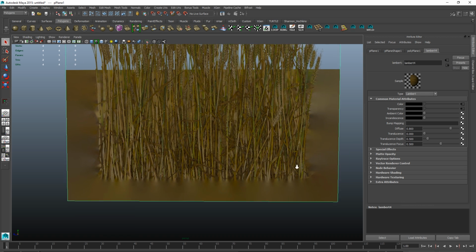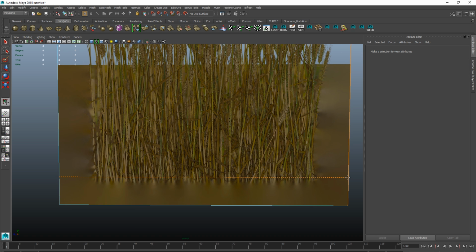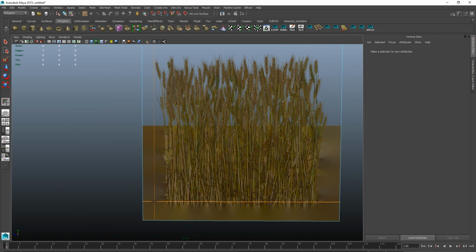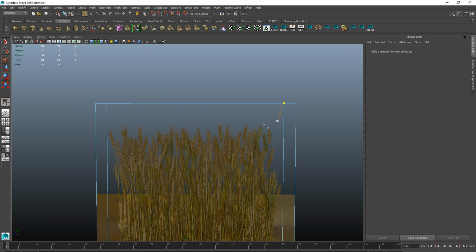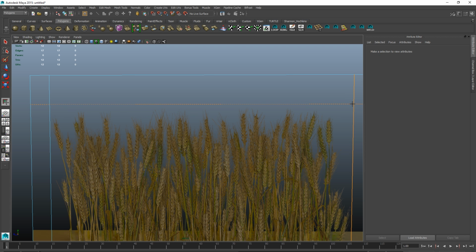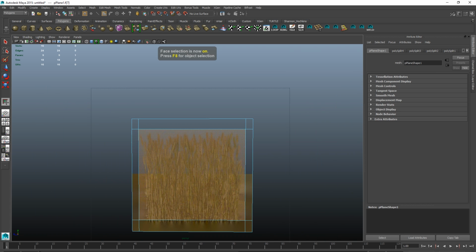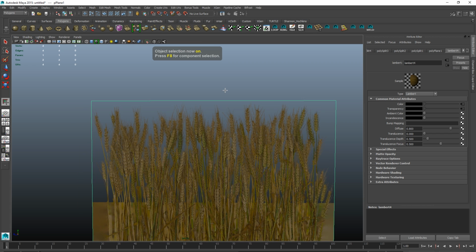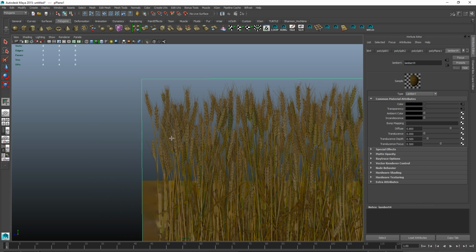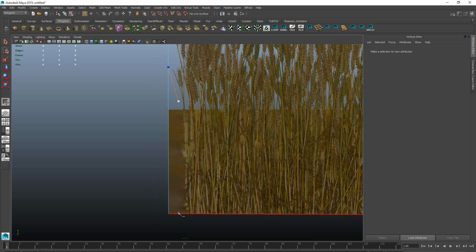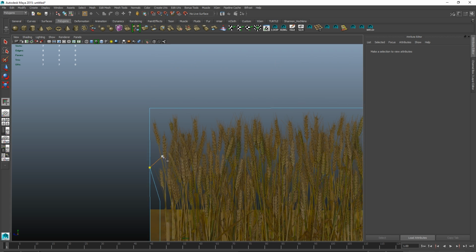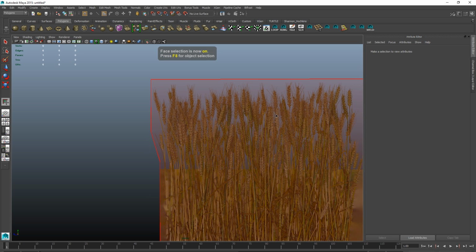So the first thing I'm going to do here is remove any excess parts that don't contain any texture information to reduce overdraw. And I'm not going to go too overkill on the matching, because you have to find a sweet spot between triangle count and overdraw. Too many triangles are not free either. So finding a nice middle ground, just roughly following the shape here.